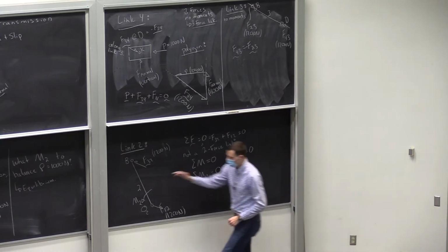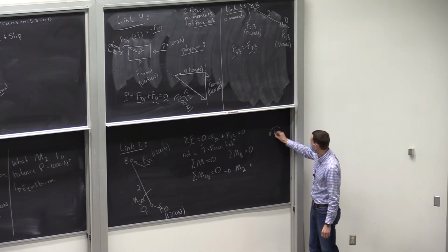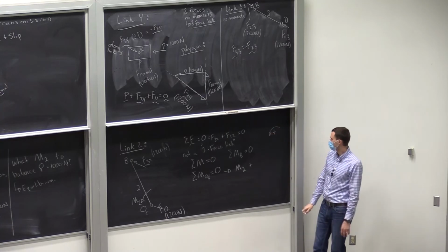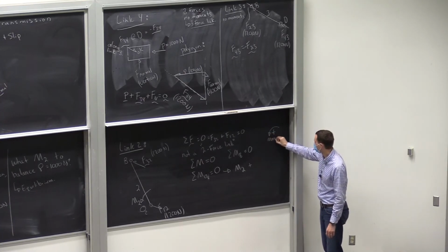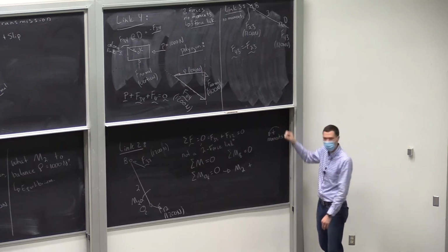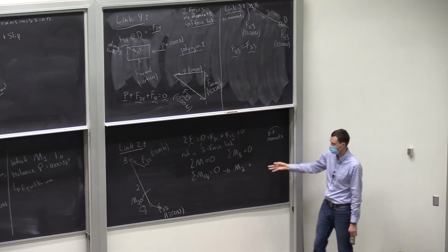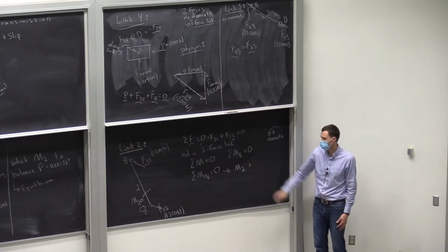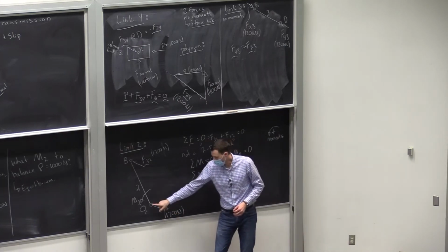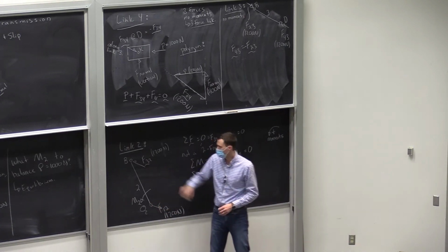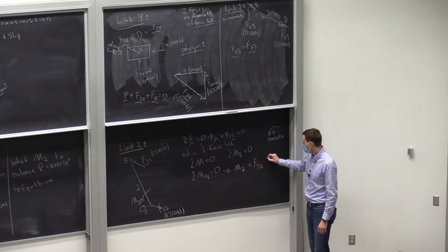Okay, and I'm going to say counterclockwise is positive. You just need to define your own standard here. That's the one I like to use. Counterclockwise positive for moments. It's not a global fundamental standard. It's just the one I'm using for writing this equation. M2 is counterclockwise, so positive. We're doing sum of moments about this point. F12 goes through that point, so it doesn't exert any moment. So we're just going to have F32 times some moment arm.